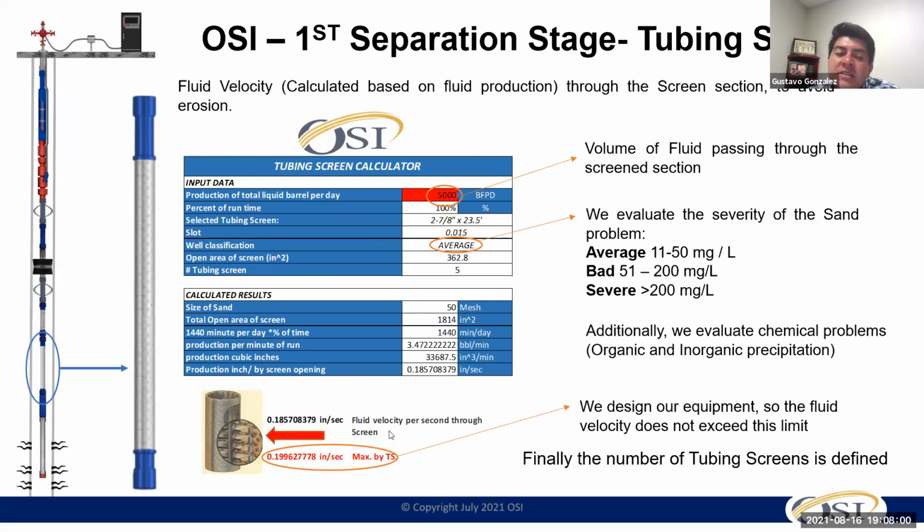What that means is, if you exceed that number, it doesn't mean that your system is going to totally fail. Wells are going to get a peak and then come back. What they try to tell you is that you cannot maintain that screen at that high rate, because your pressure drop is going to start increasing. And if you don't have enough open area and the fluid rate keeps increasing, you're going to get a jetting point, and that jetting is going to start affecting the screen.